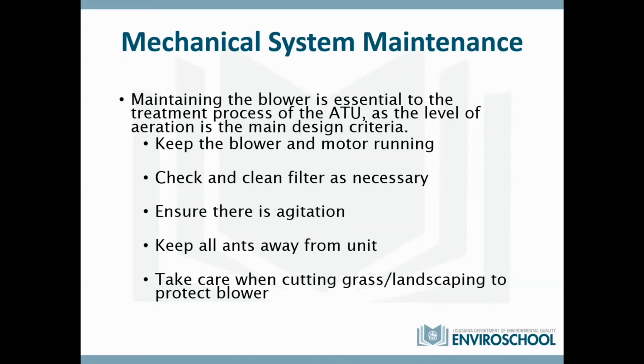And any variation in that could potentially upset your system. So keep the blower and the motor running. Check and clean that filter as necessary. Remember, we were showing a picture of one of these housings where the motor is located, and there's usually a diaphragm in that motor, and it's sucking air in through a filter. Check that filter every so often to make sure grass clippings haven't gotten into it or too much dust.